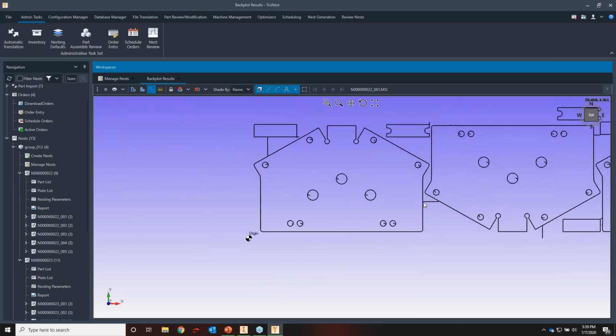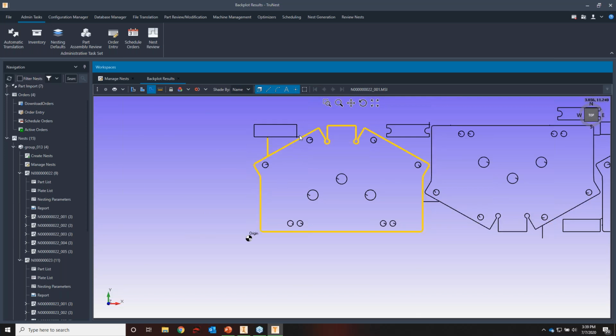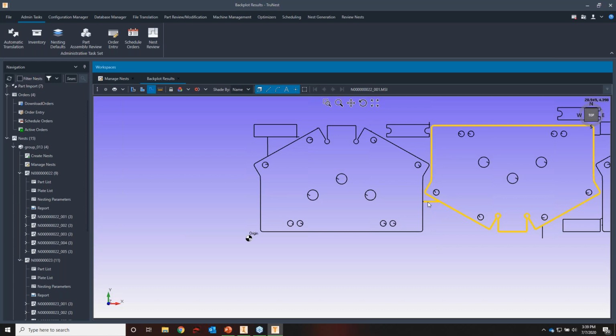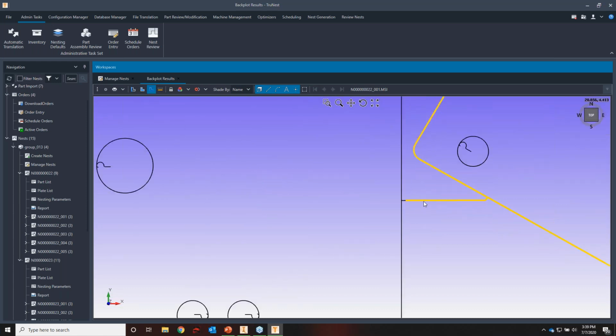And that's so that we make sure the quality of the parts is not sacrificed when we're cutting these out. If this happened to be on the other side, this part could end up snapping back due to the internal stresses in the material, things like that, and end up getting ruined just from having this lead on the other side of the particular piece of geometry.